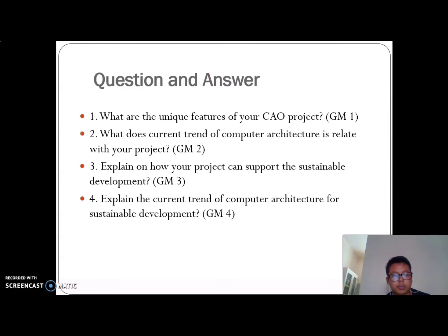And DMA transfer overcomes the problem of occupying the CPU the entire time it's performing a transfer. So in a DMA transfer, the CPU initiates the transfer, then it does other operations while the transfer is in progress, and it receives an interrupt from the DMA controller once the operation is finished. And this is especially useful in real life computing